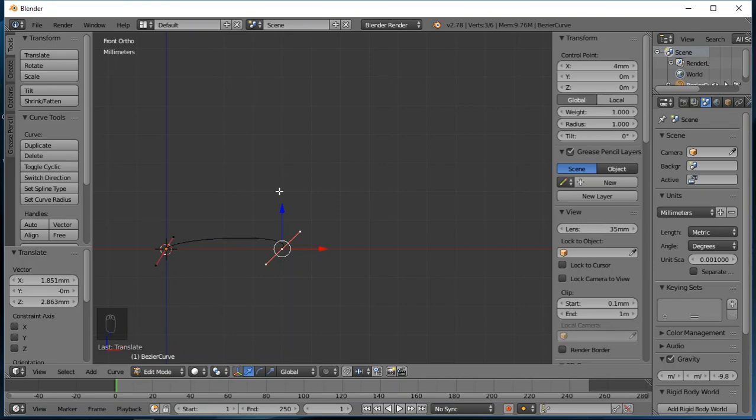And I'll start adding by a control left mouse button, adding more vertices. So I want to step up 3.5 millimeters in the Z, and I still want the X to be 4, so that will get it right to the face of the bore. And another control, and then I want it to step out maybe another 3 millimeters, so right around 7.5 would be good in the X, and 3.5 in the Z, so it's still the same coordinate.